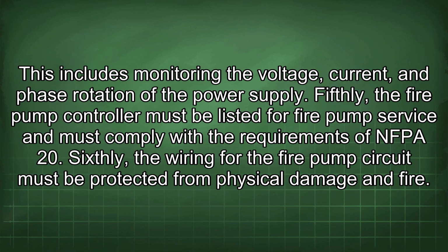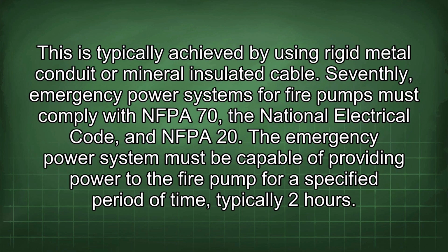Fifthly, the fire pump controller must be listed for fire pump service and must comply with the requirements of NFPA 20. Sixthly, the wiring for the fire pump circuit must be protected from physical damage and fire. This is typically achieved by using rigid metal conduit or mineral insulated cable. Seventhly, emergency power systems for fire pumps must comply with NFPA 70, the National Electrical Code, and NFPA 20. The emergency power system must be capable of providing power to the fire pump for a specified period of time,